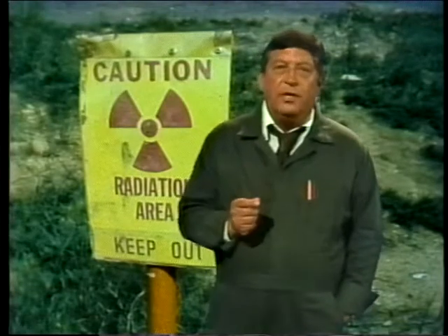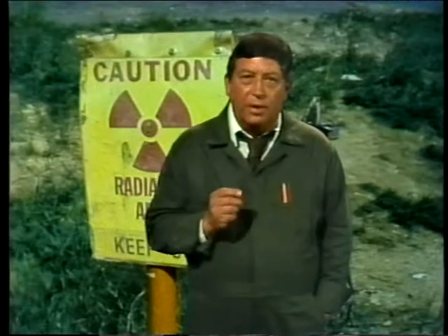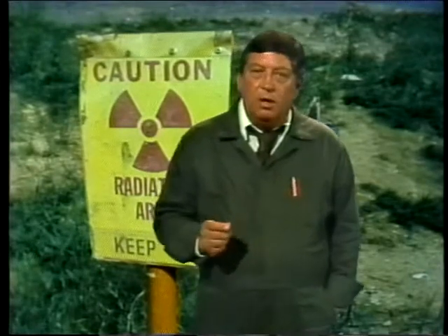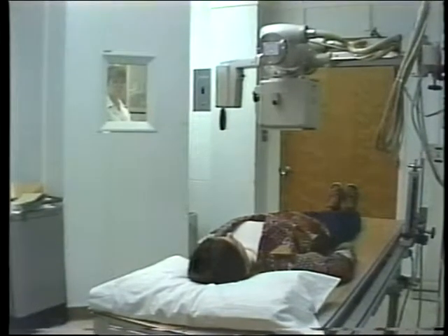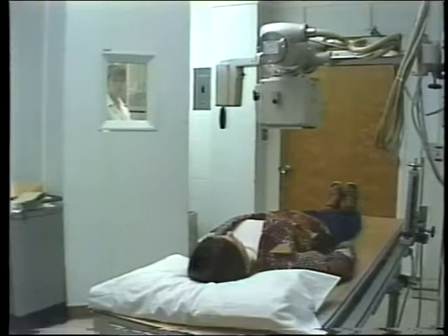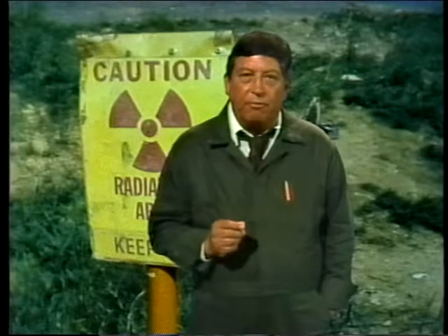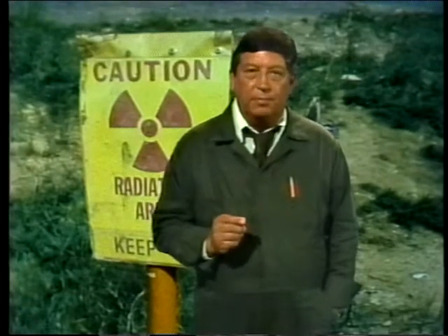The main disadvantage of radiographic inspection concerns safety. Everyone in the area of a radiographic test must be protected from the radiation used to perform the inspection. Now, basically, radiographic testing is similar to a medical X-ray. Just as you have to remove any clothing with snaps or zippers that might show up on the X-ray, the part being inspected must be free of any foreign material that might show up and raise a false indication.